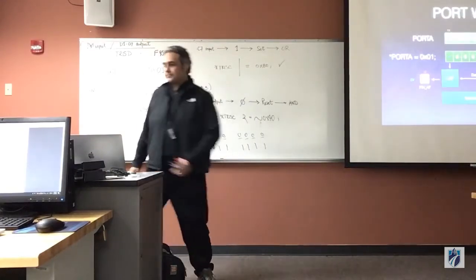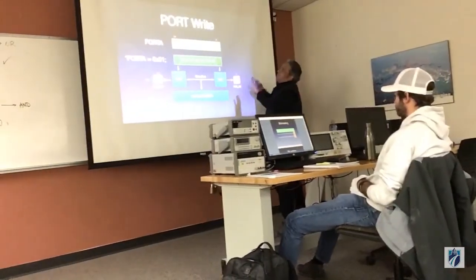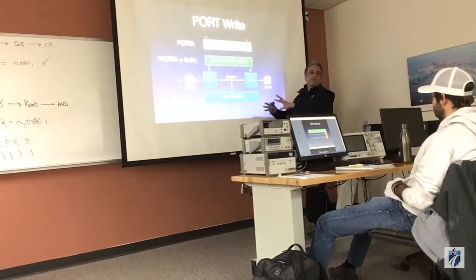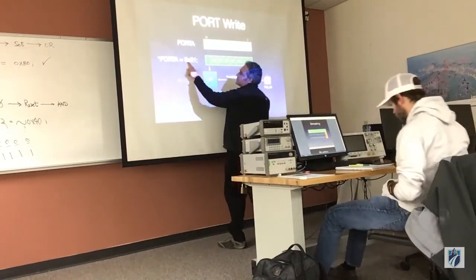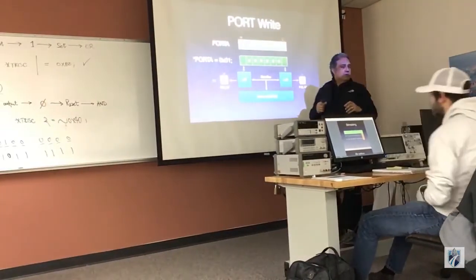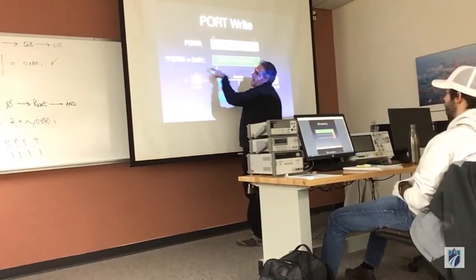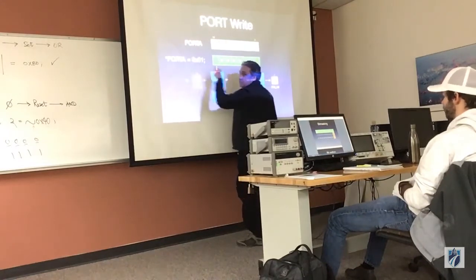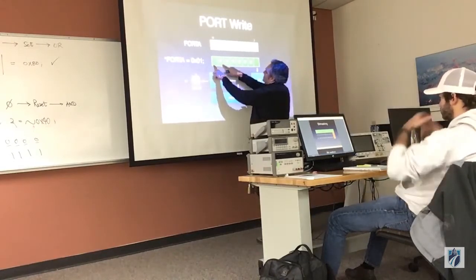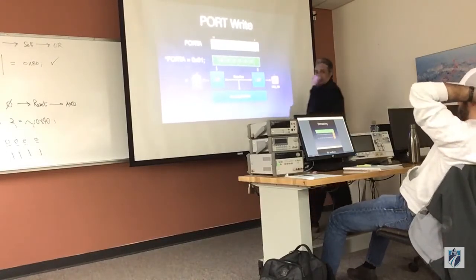So let's take a look at the write operation. Okay, once again, if I am going to be doing a port write, the behavior begins with software. So you start looking at this from this position. Right? You initiate the write. So in software, I write this number into that register. What that does is that it puts the number 0000, that's the first 0, and then the last 4, 0001.